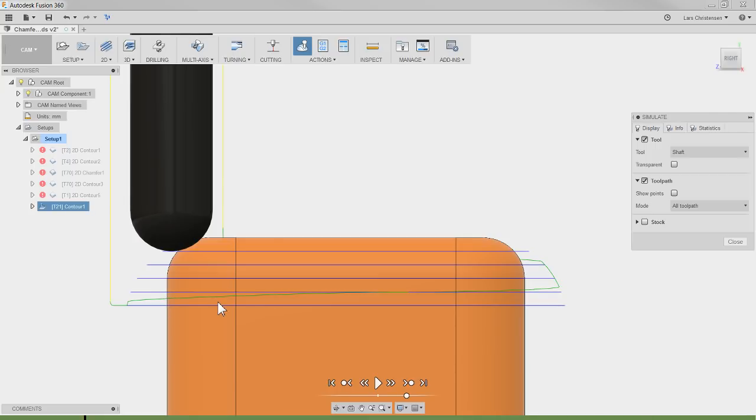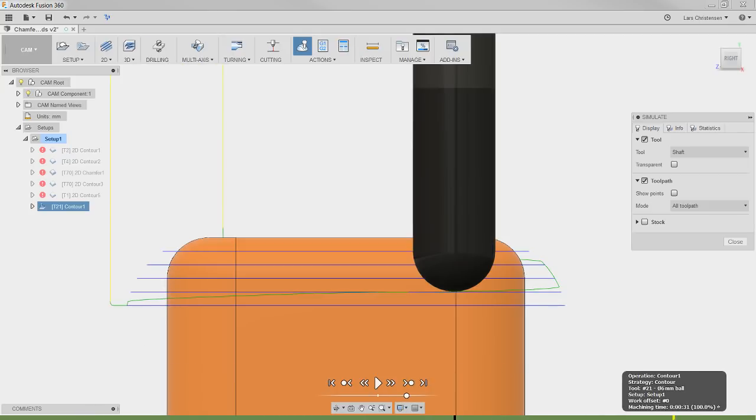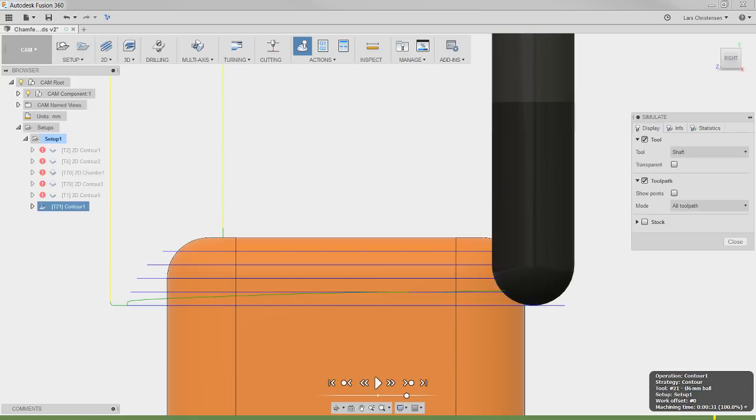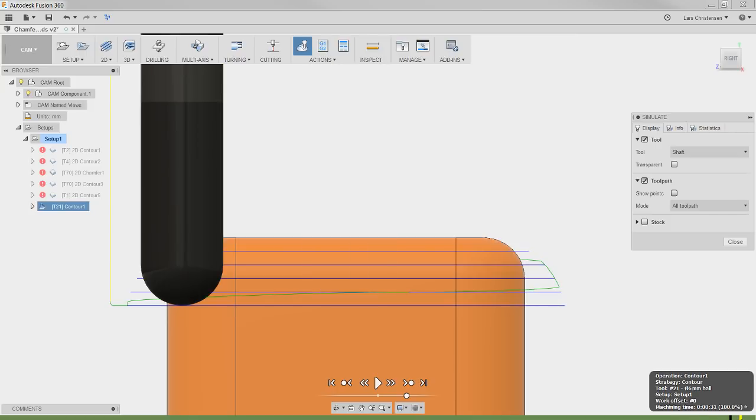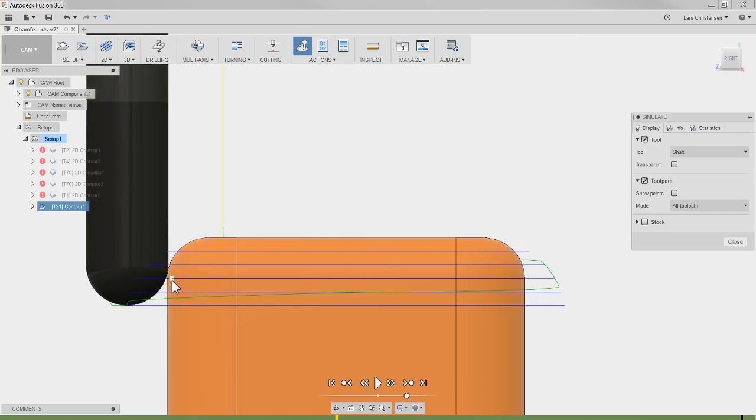But when you check contact boundary, what it does is it makes the cutter go past that, but just stay tangent to what we have selected. So you will see when we get over here that the cutter, this is still the area. You will see how the round lets it go past, but it only machines this. It's just tangent to there, and that's where it ends.